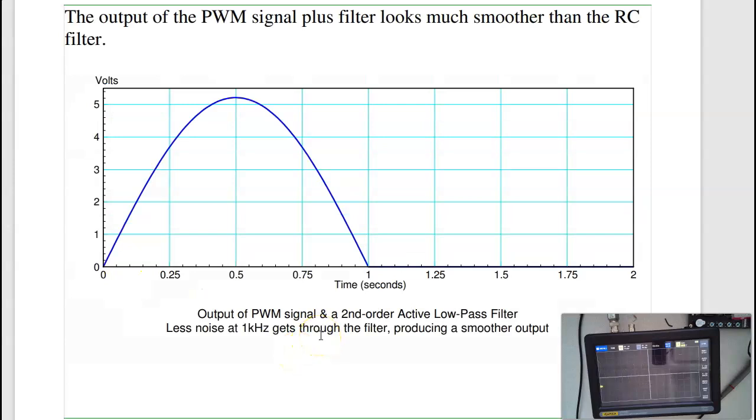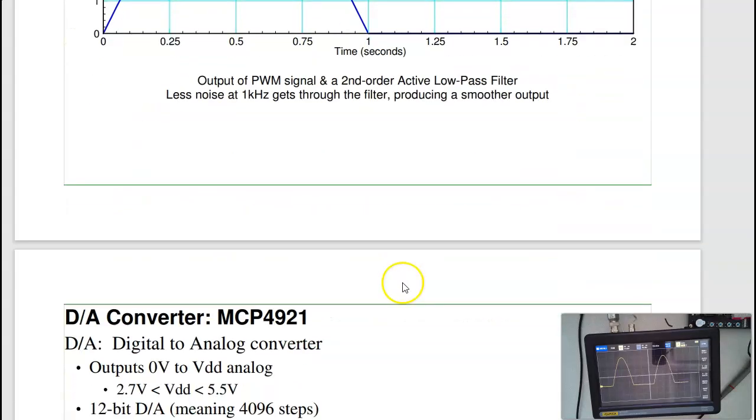So that's with the PWM output. And actually, with the Pi Pico, it's really designed for PWM output. It is really, really convenient to output analog voltages using PWM. So that's the main way that we do it nowadays.